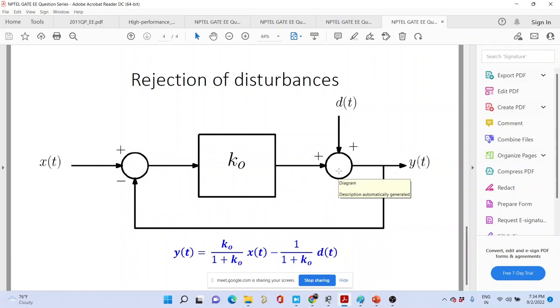In this case, this is a filter problem and we are not using any sensor over here. Whatever problem you would be dealing with at your undergraduate studies, the unity feedback problem, is actually a filter problem in which you are not investing in a sensor. Whenever you place some sensor in this feedback path, there will be some kind of disturbance over here, and this disturbance is related to the output in a similar manner as the input is related with the output.